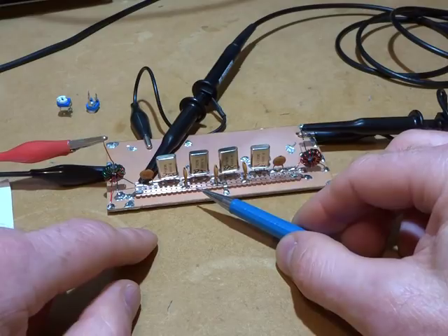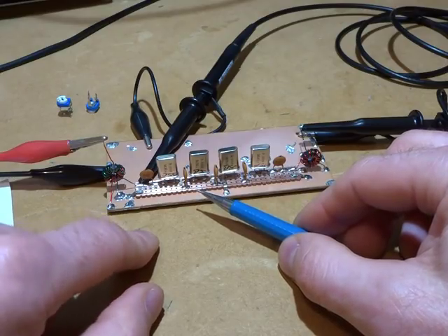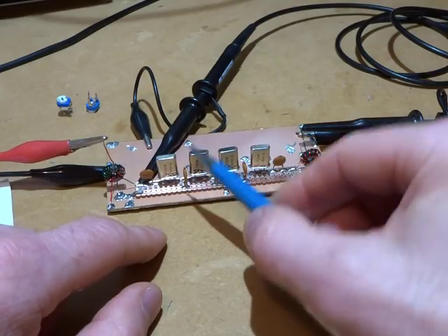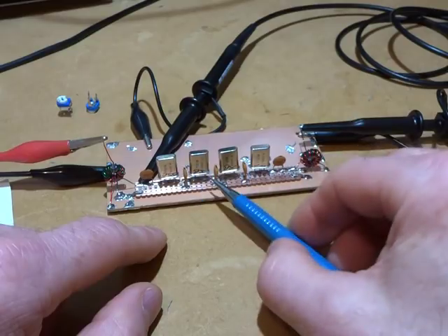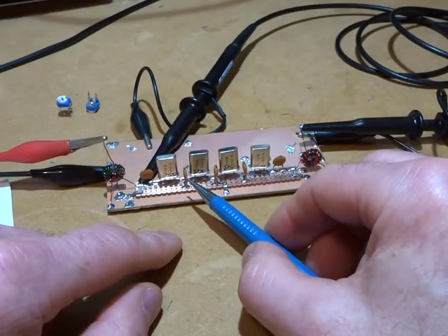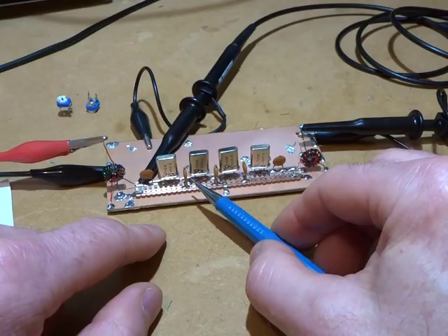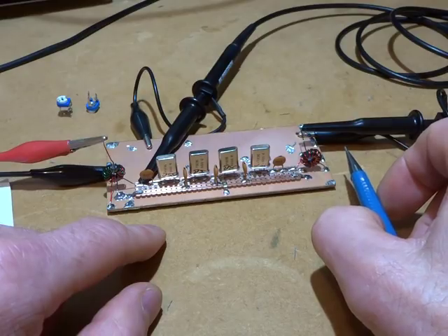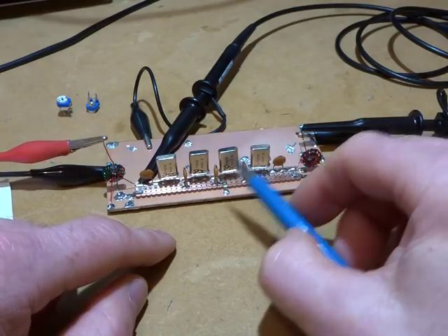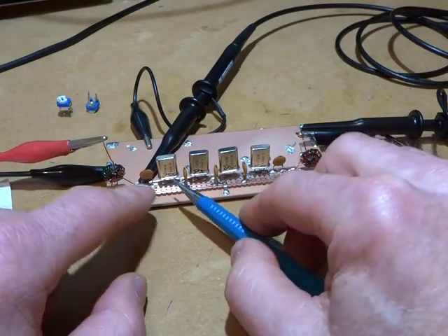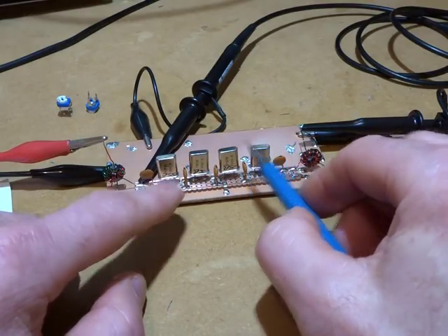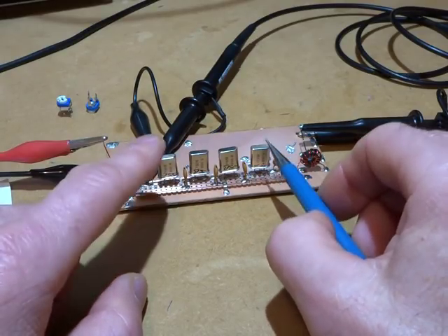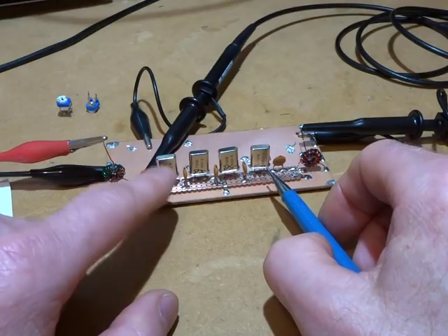But potentially the stop band rejection is not as high as it could be. It could be that because these crystals aren't the highest spec crystals in the world, maybe there's a need to increase this up to a 6-pole filter to improve that. Again, I'm not too sure. One part of me thinks just to leave the SSB filter as it is. The bandwidth is about right. The skirts seem to be relatively steep between the -3 and the -6 dB points.